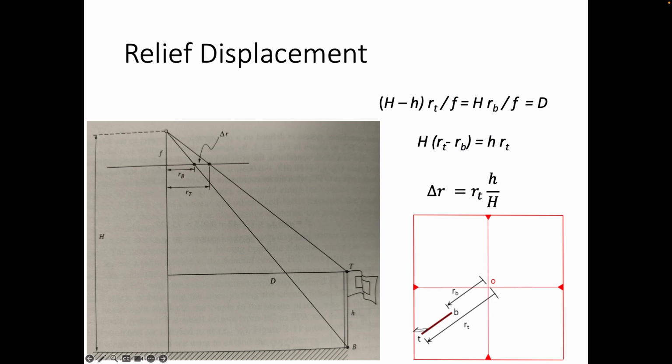So what we're going to talk about today is sort of similar to what we talked about in the last video, where you have a perspective center, you have the projection of your three-dimensional real-world object onto this image plane, and the image plane has a coordinate system of its own. And so you can use the location and relief displacement of objects in that and sort of think about it in terms of this geometry and similar triangles to work out things like the height of a particular object if you know the height of the camera, the distance in the image, and the relief displacement.